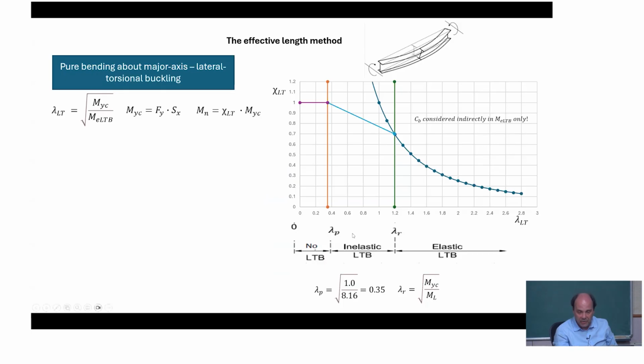Then on the other end, we have the long members with high slenderness, where AISC adopts the Euler moment, the Euler stress value, as strength. And then there is this intermediate part, which was also part of the discussion, whether this should be moved or not with the CB, or yes, then just simply by multiplying, or not, or doing something more.